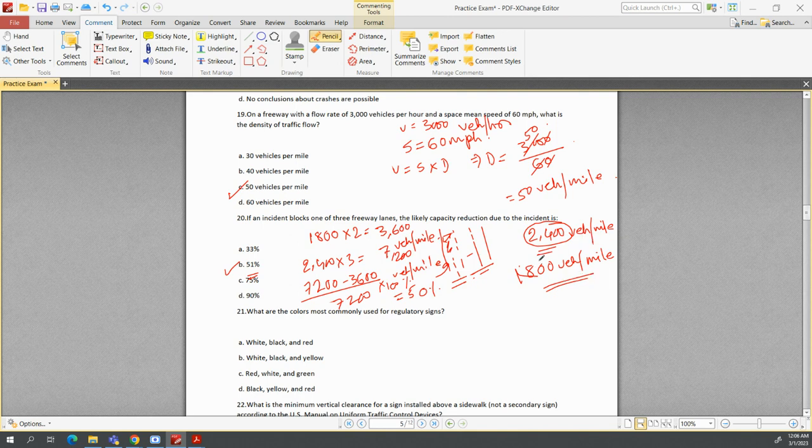And this is also generally 1800, 1900, something like that, in that range. Because when this lane cannot function anymore, the other two lanes' capacity will reduce. It cannot address the demand of 2400 anymore, right? So it drastically reduces. So that will be the answer.